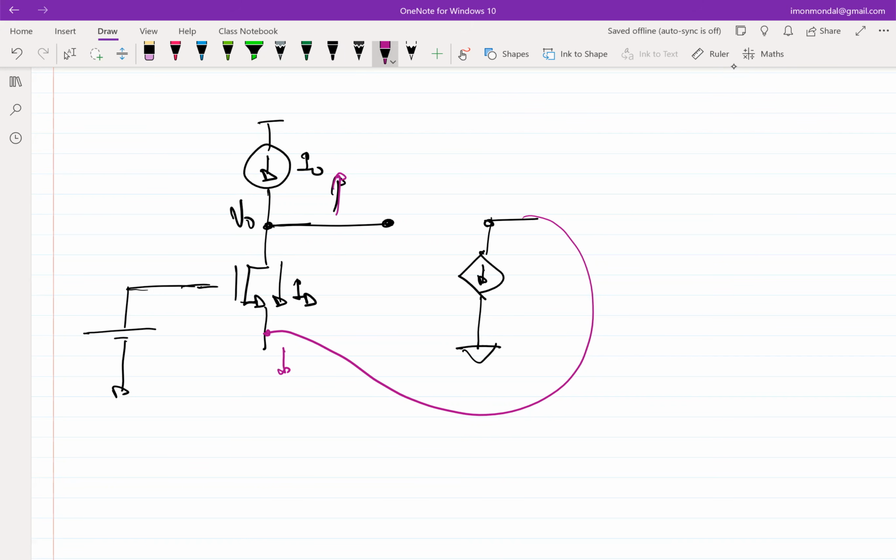And I know that if I have a voltage control current source, which is essentially a MOSFET, and if I observe the drain of the MOSFET and I increase the gate voltage, this is exactly what we end up with, right? So what is the obvious conclusion here? The obvious conclusion is that I observe this voltage V naught, and drive a current GM2 times V naught out of this node.